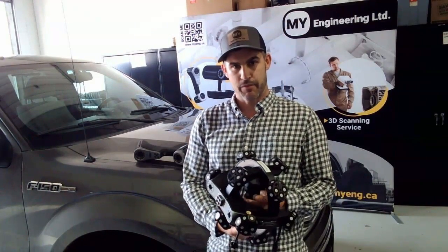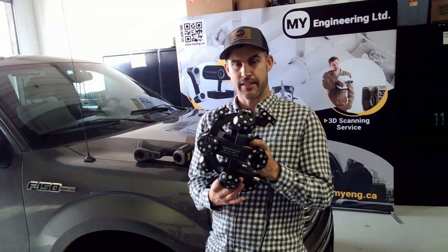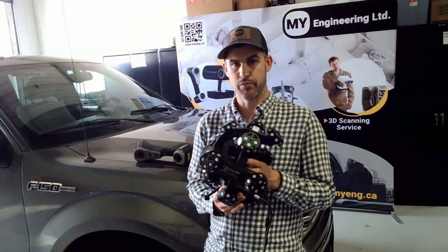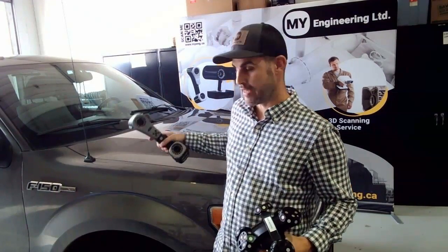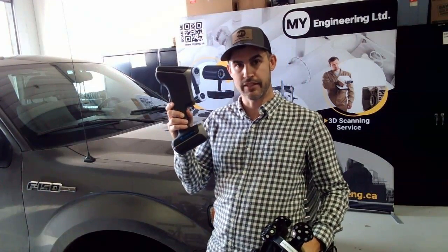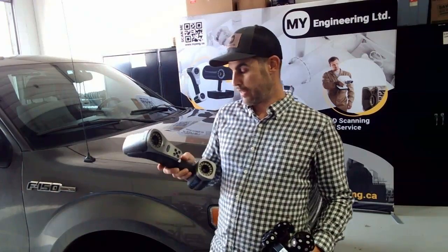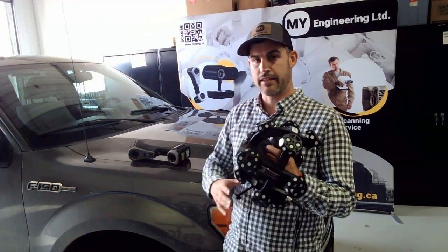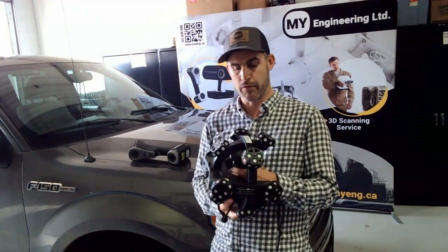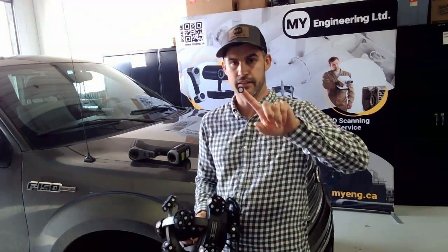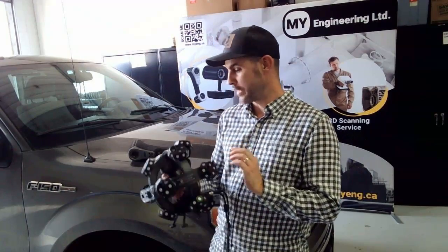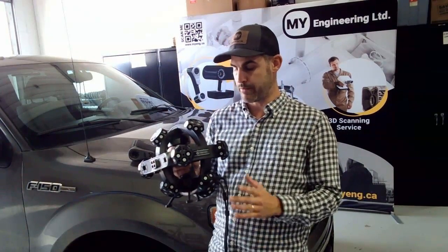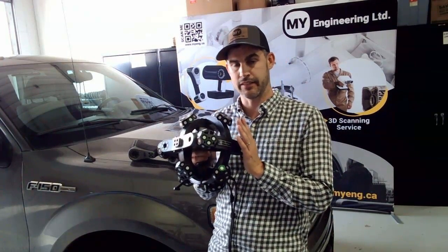A little bit about the scanner before we get going. This is the Scantech Trackscan Sharp. It is a blue light laser scanner. You may notice it looks a little bit different than other scanners that you may be familiar with. This one is the KSCAN-Magic 2. The advantage with the Trackscan is it does not require any marker dots, so that is these little stickers that you would have to apply to the object that you're scanning, because there's a tracking unit behind the camera and it tracks where the scanning head itself is.